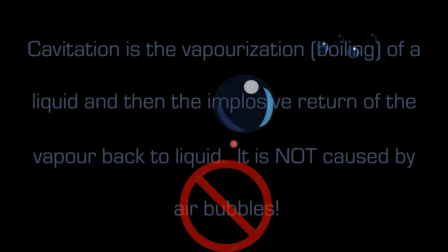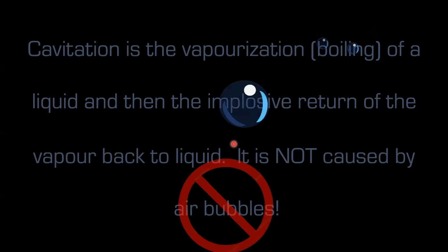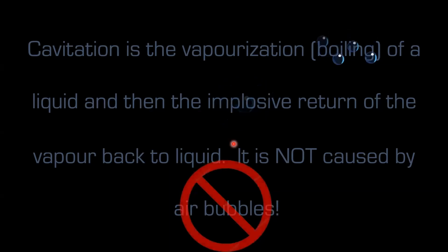Cavitation is the vaporization or the boiling of a liquid and then the implosive return of the vapor back to liquid. It is not caused by air bubbles. And I say that because a lot of people do think it's air bubbles, and it definitely looks like air bubbles. Chris and I and several of us take around the glass face pump. And when we get that thing cavitating, you would swear that the cavitation bubbles are air, but they're definitely not.